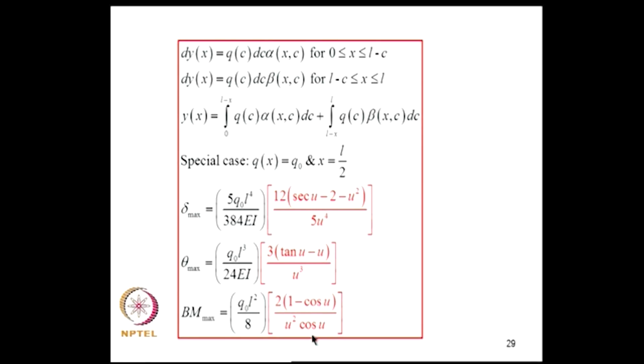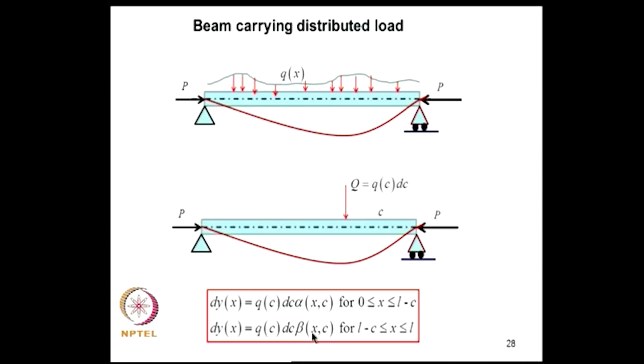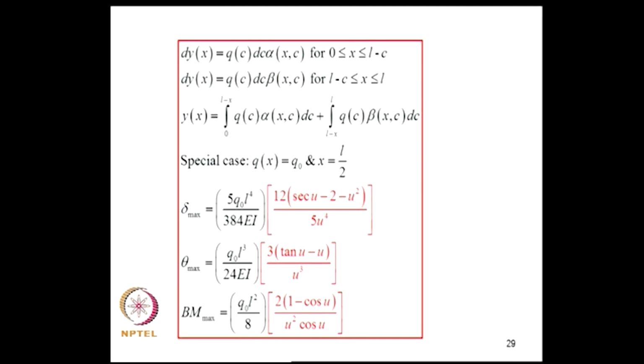Okay. So, in a problem where there is a transverse load Q of x, if there were to be an axial load P, and if this P happens to be in the neighborhood of the critical load, then the response of this frame due to Q of x will be substantially amplified, and this is undesirable. Therefore, our interest in this subject.